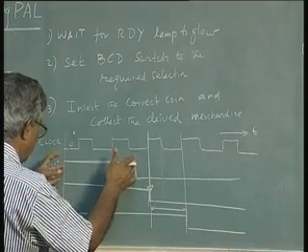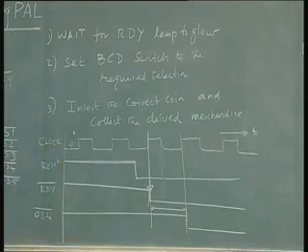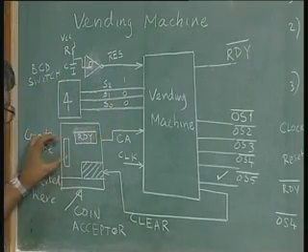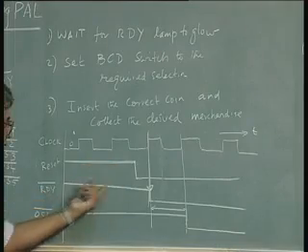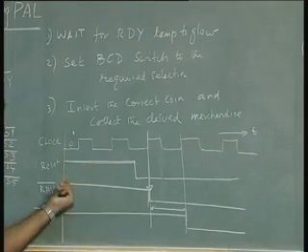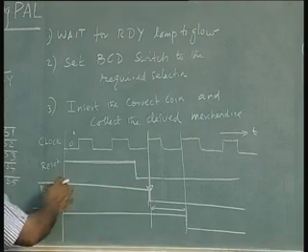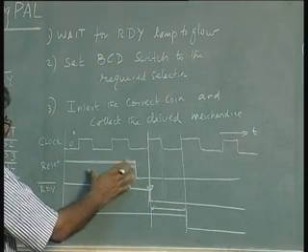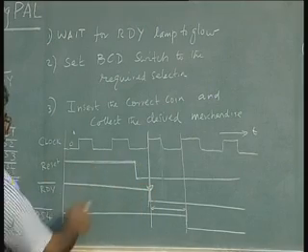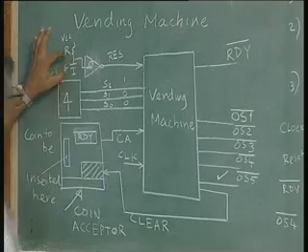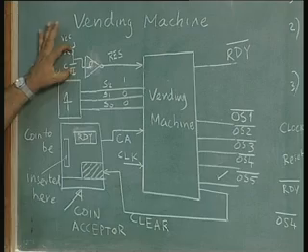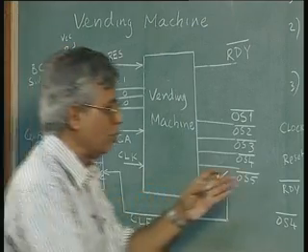Reset high is the period where the machine will not accept the signal from input or the coin ready, and only once the reset is over will the ready signal go on. That is why the ready signal has been shown as coming after the reset. After the reset is over, it is asynchronous. The timing depends on the charging of the capacitor. The RC time constant decides the time for which the reset is going to be high.